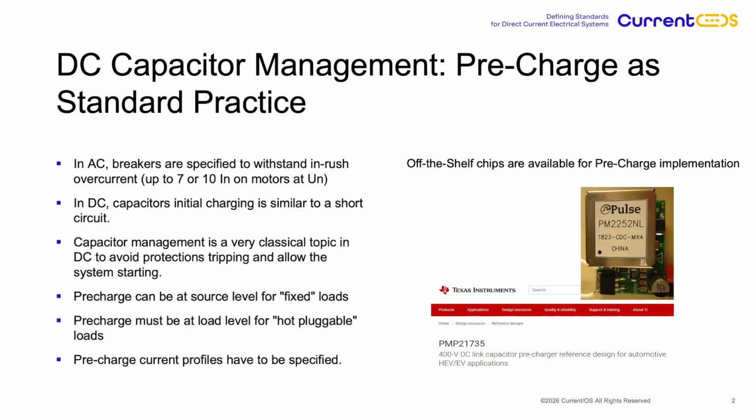In direct current systems, capacitors are everywhere. This creates a significant challenge. At startup, they generate very high inrush currents. It gets even more critical. An empty capacitor essentially acts as a short circuit. Without proper management, this could trigger all the protections the moment the system powers on. To avoid this, every DC device must include a pre-charging system.